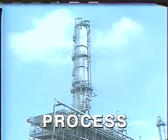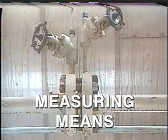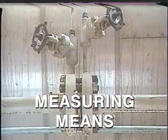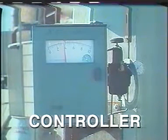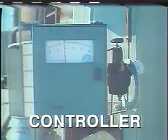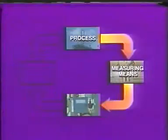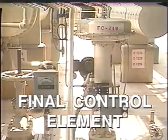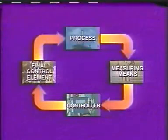In any control situation, whether the equipment is a process furnace or a home heating furnace, there are 4 things that are necessary. First, there is a process that needs measurement and control. For each process variable that must be controlled, there is a measuring means, one or more instruments that can measure the process variable. There must be some kind of control mechanism to receive the measurement information and determine how it compares with the desired value or set of values. The control mechanism must also tell the valve what action, if any, the valve should take. And there is a final control element, which is usually a valve. The final control element makes the actual process change that keeps the process variable on target.